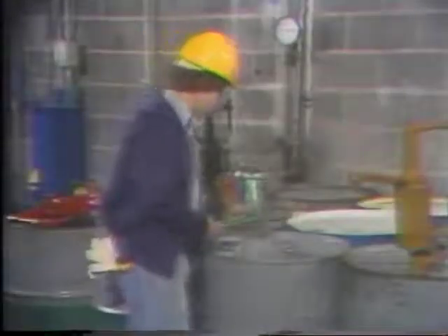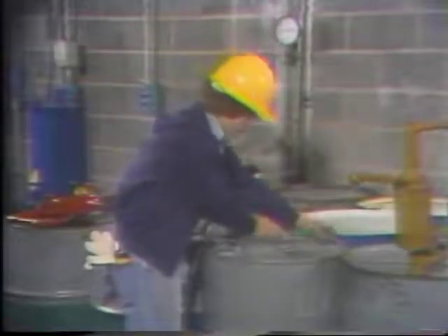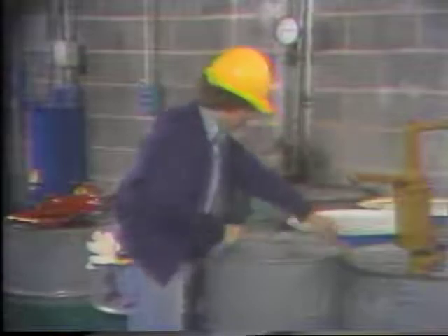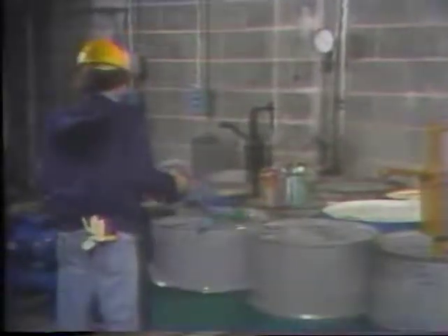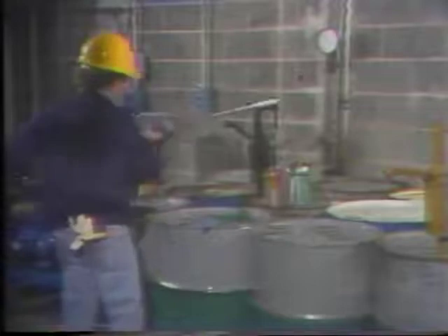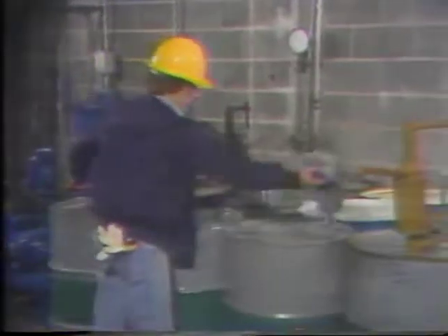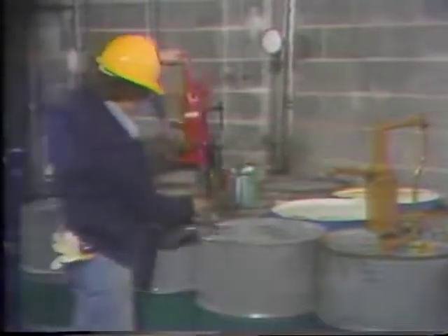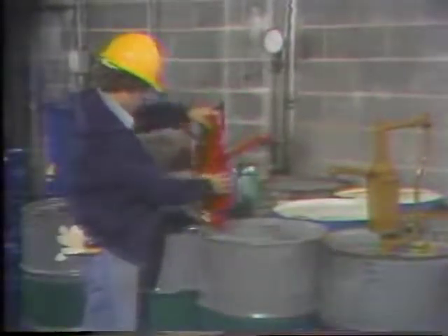For the pump to operate properly, the barrel usually needs to be vented. This is done by removing the small vent cap on the top of the barrel, as you see here. Another job that must be done is cleaning the barrel pump. These pumps can sit around for a while and dirt may collect on them. Once cleaned, the pump is inserted through the open hole in the barrel and screwed into place.